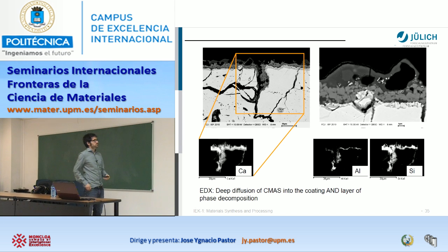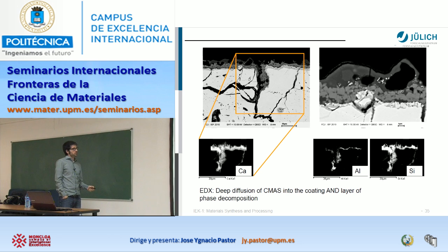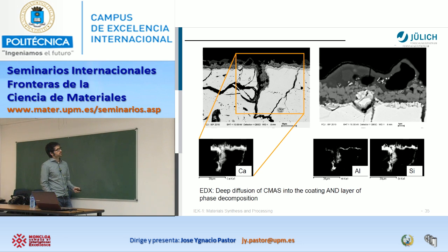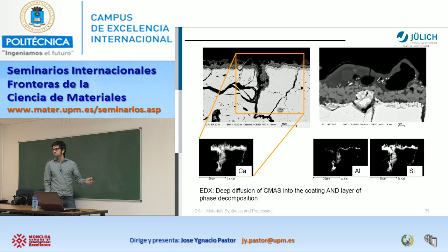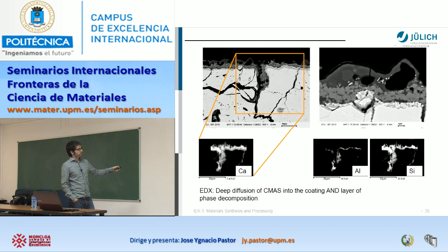Well, and here just a few examples of the penetration of these elements that are really critical. For example, here the calcium, obviously they start to penetrate through the cracks. Here by EDX, you know what is EDX technique? Well, that you can do with EDX, it's basically that you can choose, for example, in SEM pictures, through the electrons, you can produce like a mapping of different elements.